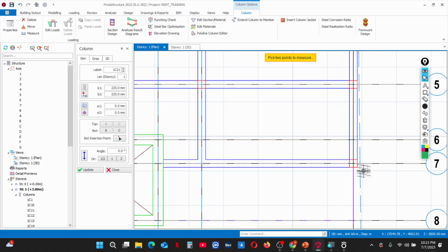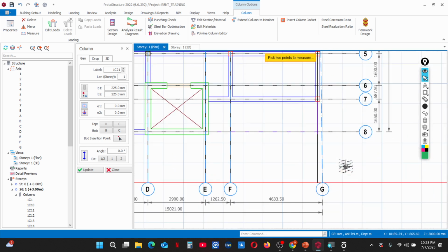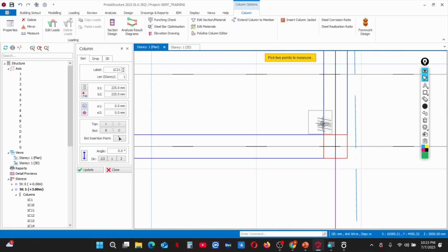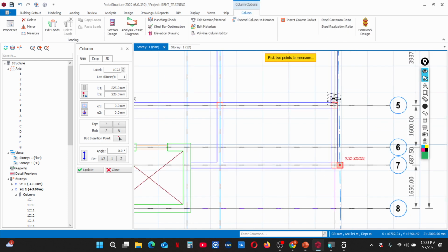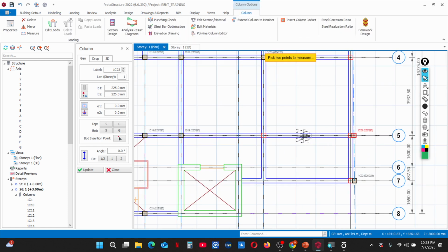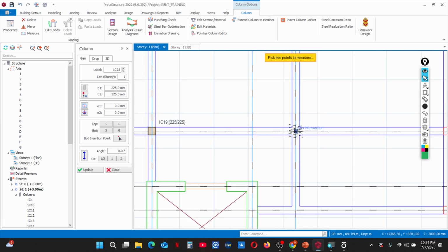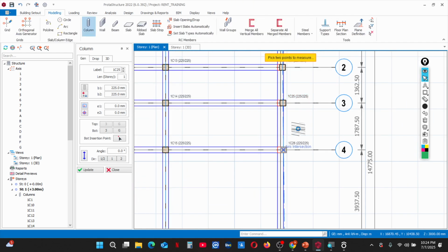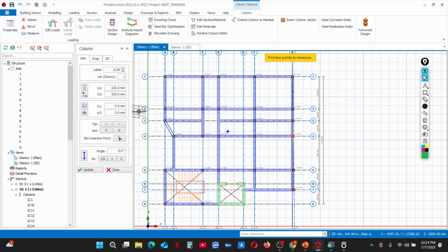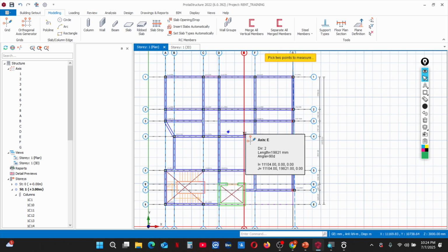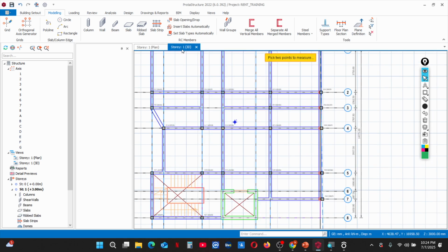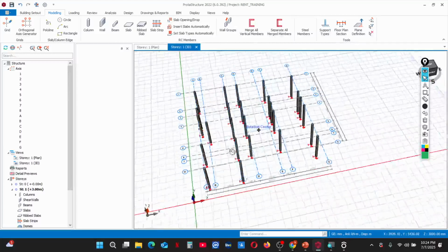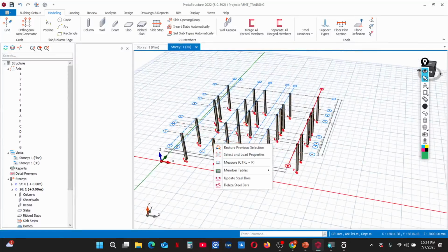Place one more over there. Okay, this axis was actually not drawn well, it's going diagonal, so that's a mistake. We are going to correct that in our external reference drawing before posting it. So let's place this one at that place and then have one here. This is what your assignment is expected to look like. Press escape. This is what you have now created. Go to your 3D view. This is what our columns are going to look like when you have finished yours.